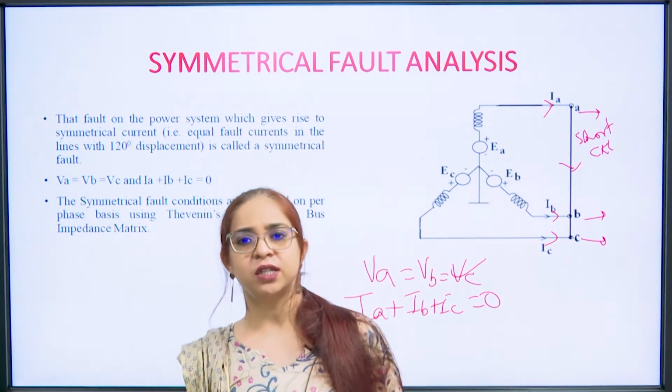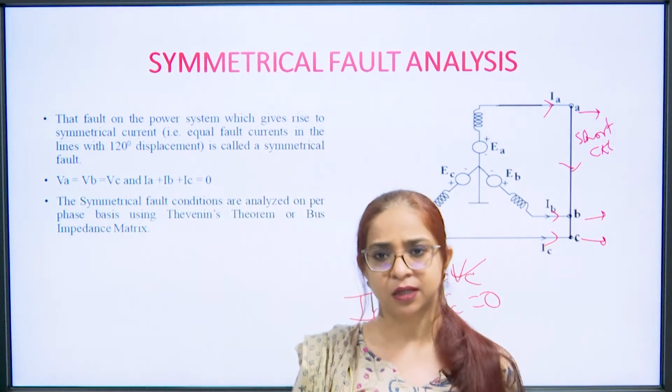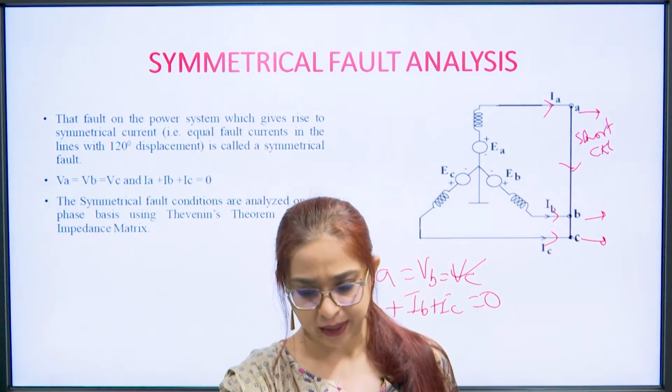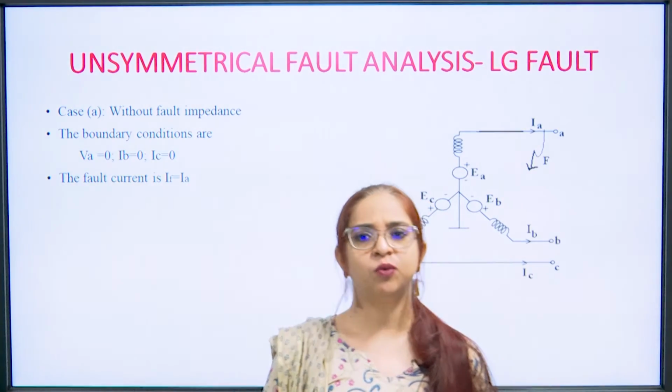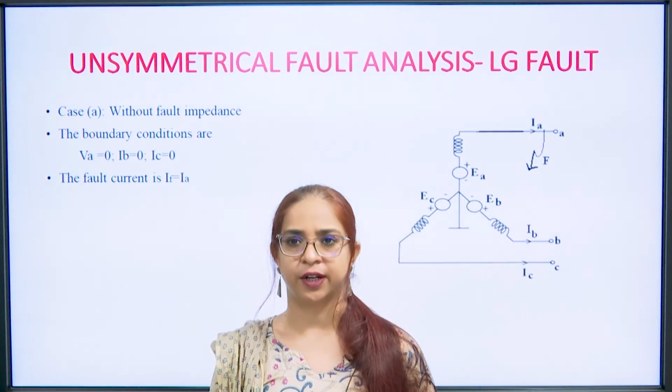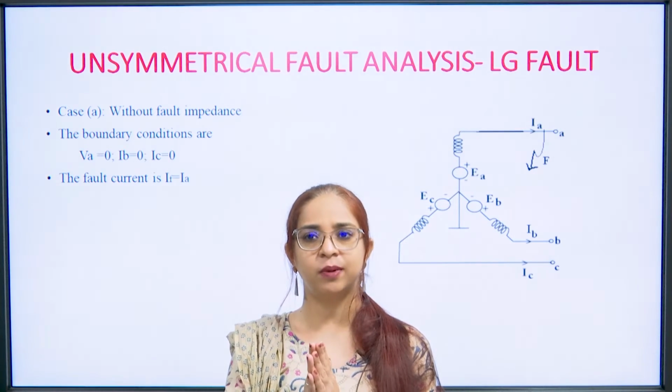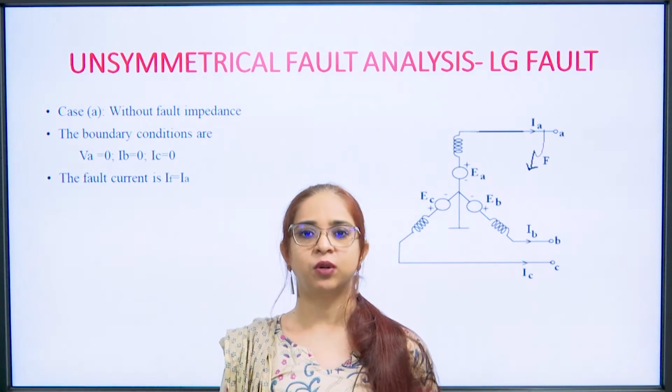The other methodology is through the bus impedance matrix. We will discuss this in an upcoming lecture. Now let's move on to the unsymmetrical fault analysis. The first case is the most common occurring fault, which is line to ground fault.